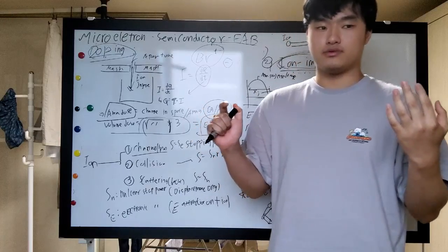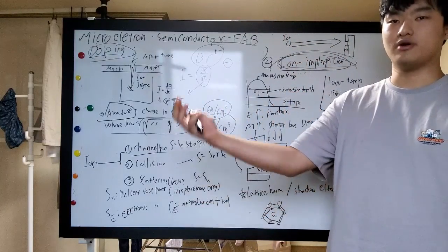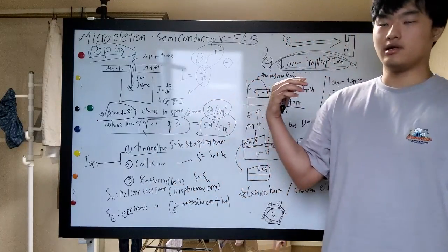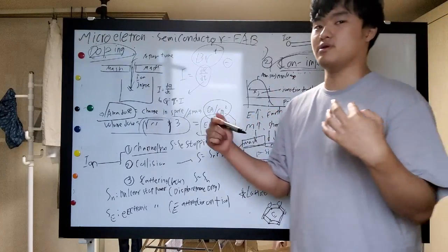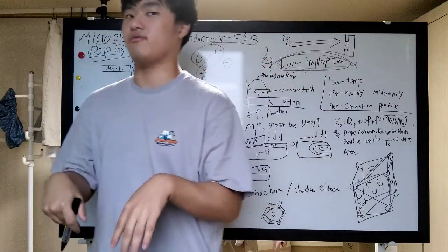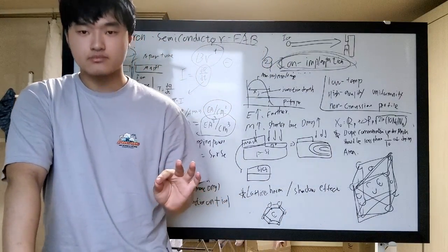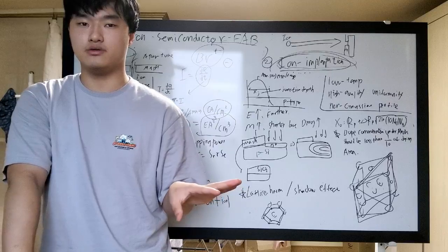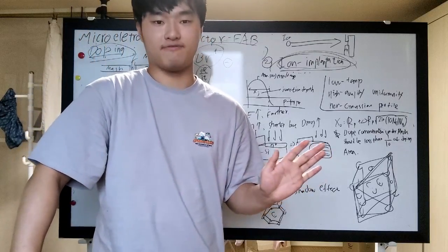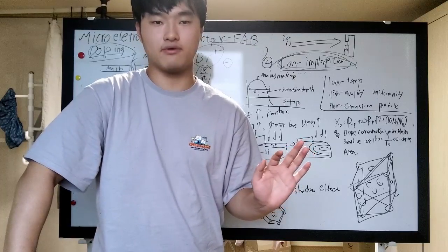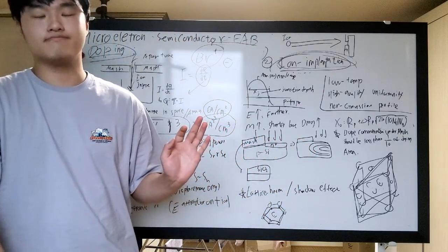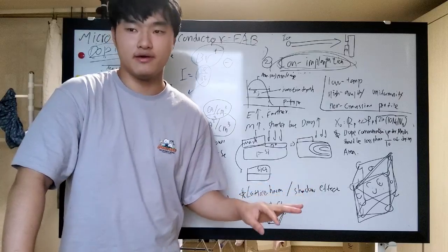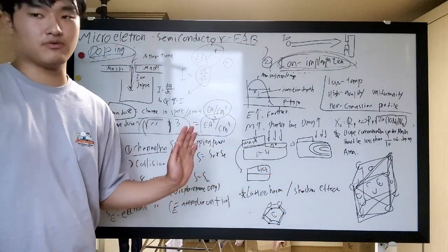The ion, having a positive charge, will be attracted to the electric field that the electrons keep making, so the ion will lose its energy and emit. Finally the ion will have less energy than planned, and may have a weakened doping effect, or even have binary collisions but can't replace the nucleus place, and can't go deep enough as we wanted.